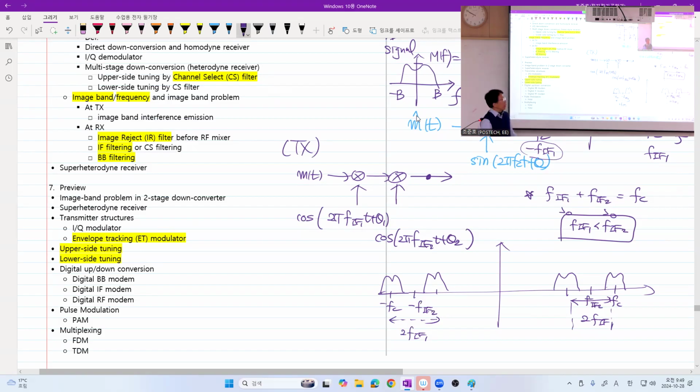Actually, that is the way, because if you want to apply this idea, heterodyning, to upper sideband SSB, probably you will have the quadrature branch like this. And as I told you, it's not easy to have perfect synchronism between in phase and quadrature at very high frequency.